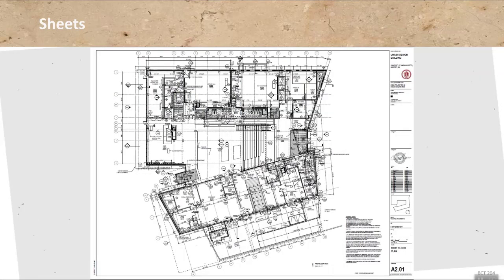And next, of course, you're going to be looking at sheets, and you're going to be looking at lots and lots of sheets of the various disciplines. I pulled out an architectural sheet here, and you can see that it's an architectural sheet by its number. So every sheet has a number. The number typically consists of a letter and a number. The letter tells you something about the discipline. So there's A for architecture, C for civil, S structural. Then we've got L for landscape, H for HVAC, E electrical. There's a fairly long list of those, and they basically organize the sheet set.